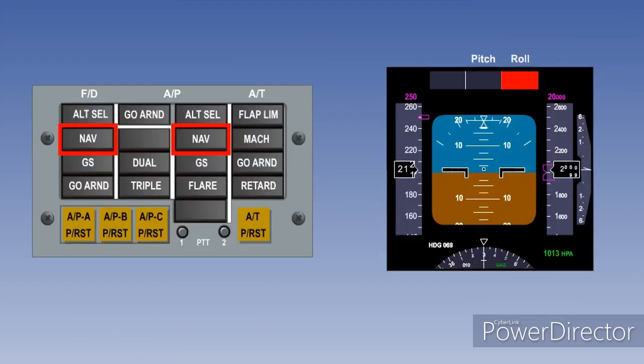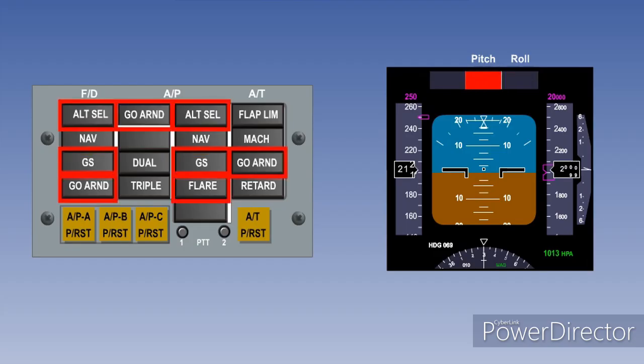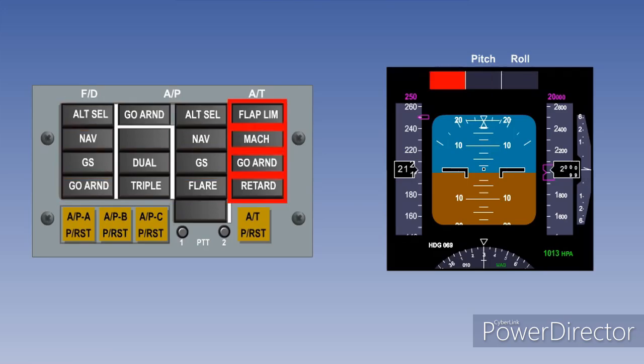We will take a closer look at the flight mode annunciators. These are vital to indicate to pilots the modes of operation of the flight directors and autopilot in roll and pitch, as well as the autothrottle mode and status of the autopilot, including automatic landing capacity.